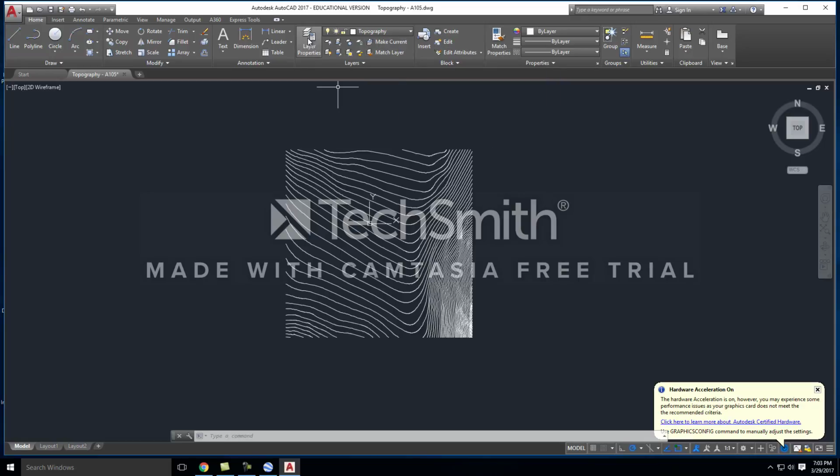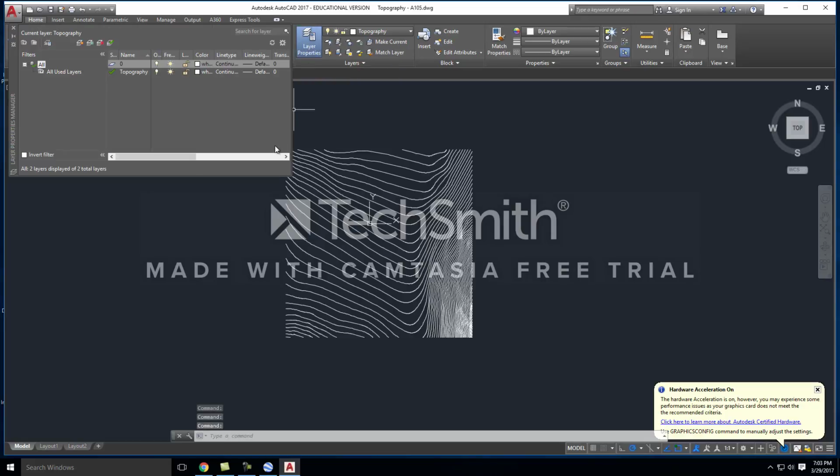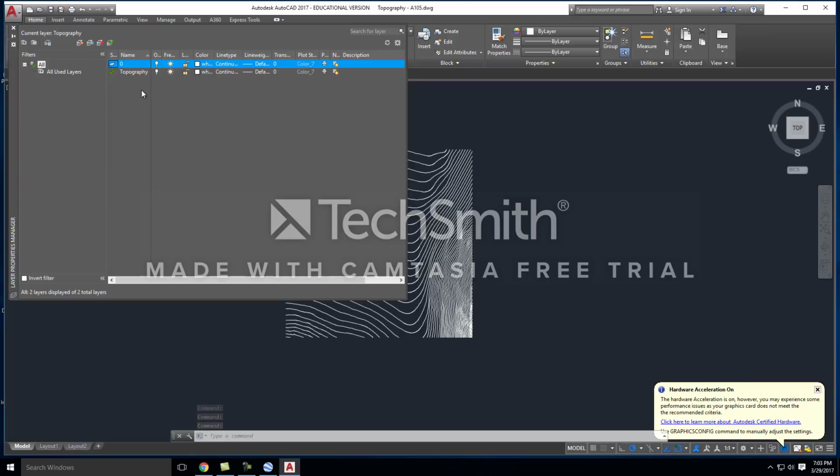If we click on this button right here that says Layer Properties, you will notice that currently we have two layers. By default, AutoCAD gives you the 0 layer, so every time you start a new AutoCAD file, you will get one layer and that will be the 0 layer. Included in this file is also a topography layer.